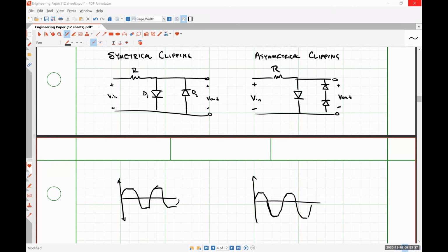So what we really mean by that is you're designing this circuit and you're going to be simulating it entirely. We're not expecting you to be able to go to Mouser or digikey.com and buy the parts and put it together. That being said, your design should use practical component values. So for instance, if you design a circuit, I don't want to see that it's going to use a 137 ohm resistor, because a 137 ohm resistor does not exist. Or if you could buy it, it would have to be a custom ordered thing.